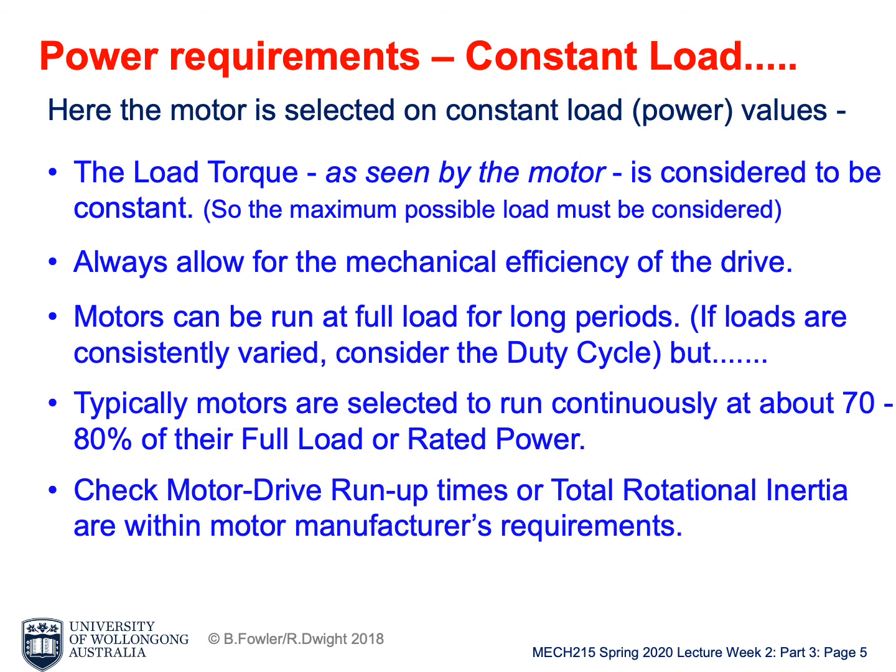One more thing we have to make sure of is the run up time. So this is the startup time for the motor. We want to make sure this time is not too long, so the motor doesn't run at very high current for an extended time, so the motor doesn't get burned down.